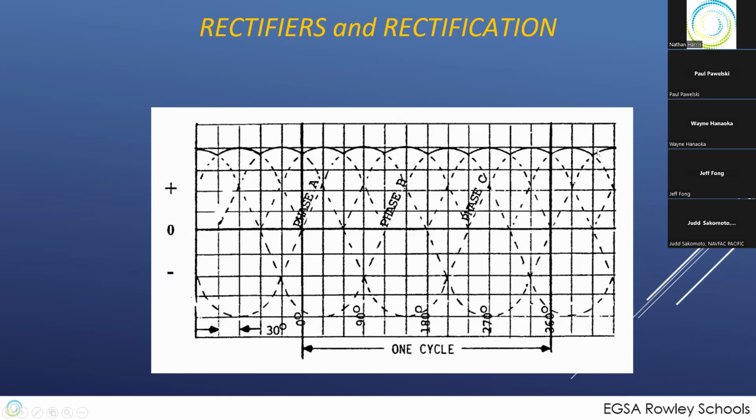So the resulting voltage measured with a multimeter is going to read 35% more than what our AC voltage read coming into it. Are we actually getting more out? No. It's just how the averaging is done to get RMS. Remember, voltage and current actually are instantaneous. RMS is just a convenient lie that makes the calculations easier.